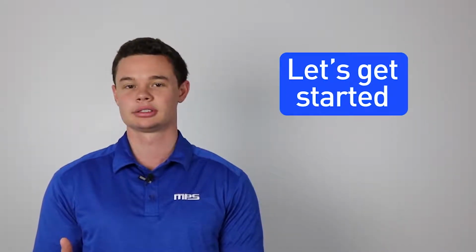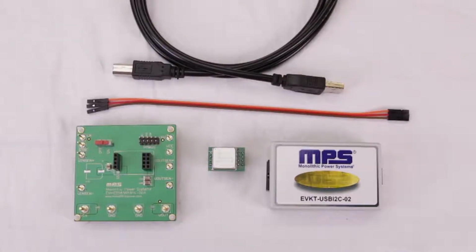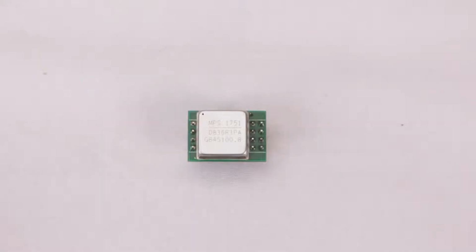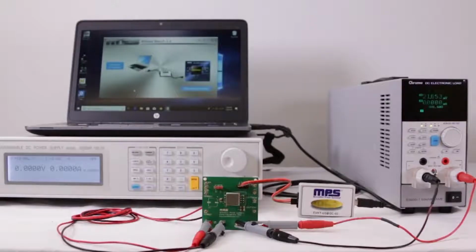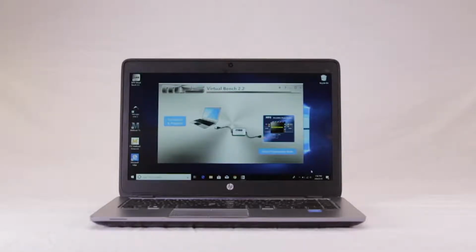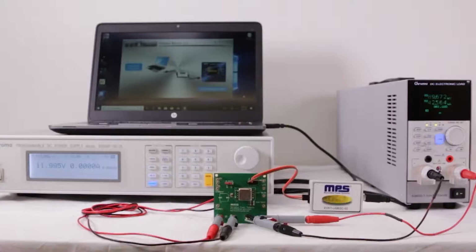Let's get started. First, we'll show you how to configure the mEZ power module using our field programmable evaluation kit, which includes an I2C communication interface device, an evaluation board, and mEZ power module. Additional equipment required includes a power supply, a DC load, and a laptop with our virtual bench software to configure the power module and run simulations.